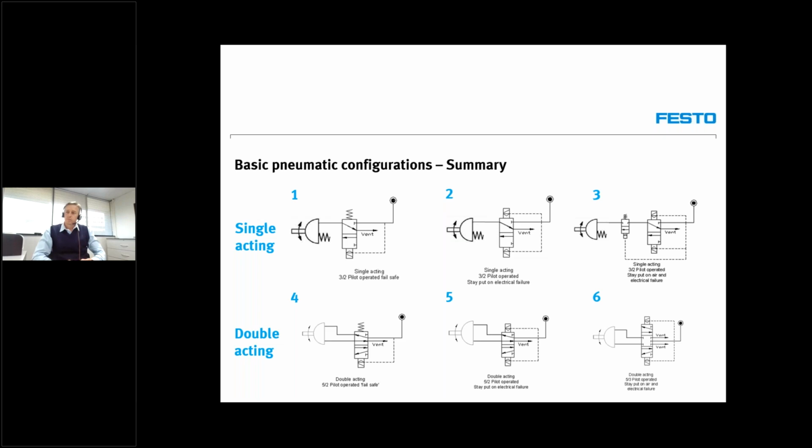So you'd imagine that if you had an air failure, you'd have to detect that, and then based upon the detection of the air failure, you'd want the device to either open or close. So you need to open or partly close a particular valve to give you the desired movements of the actuator that you're driving. It's a very interesting topic and certainly very doable in the pneumatic world, but it does require understanding of some basic pneumatic circuitry and components.